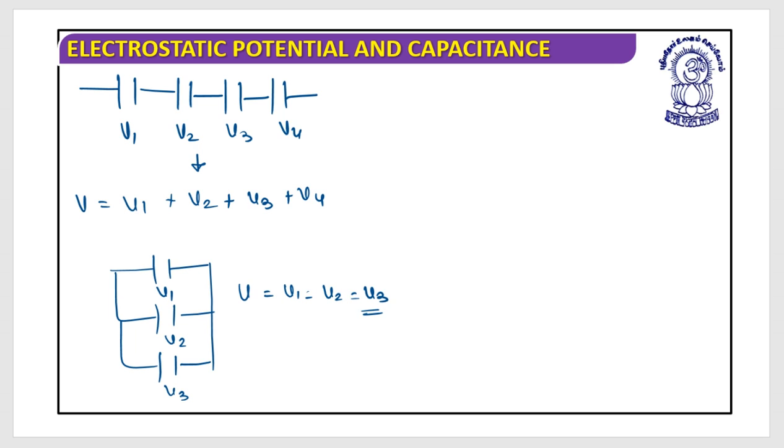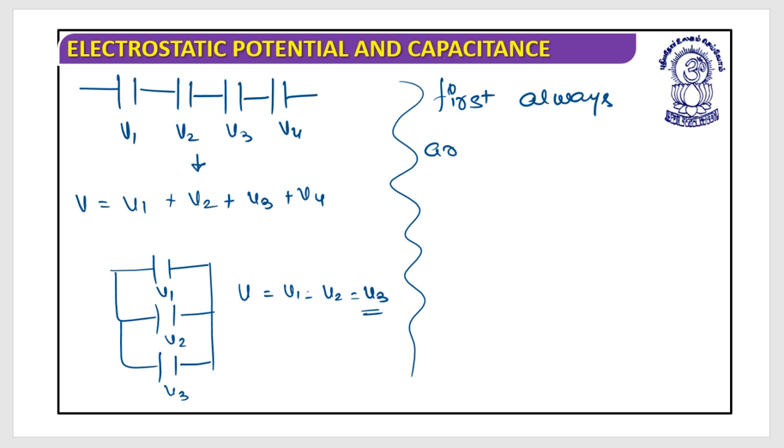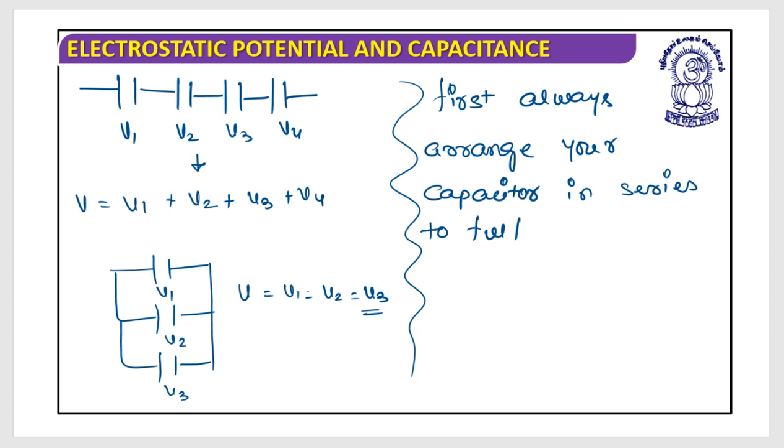Yes. So when this kind of question has been asked, always remember that as a first task, always arrange your capacitors in series to fulfill the requirement of voltage.